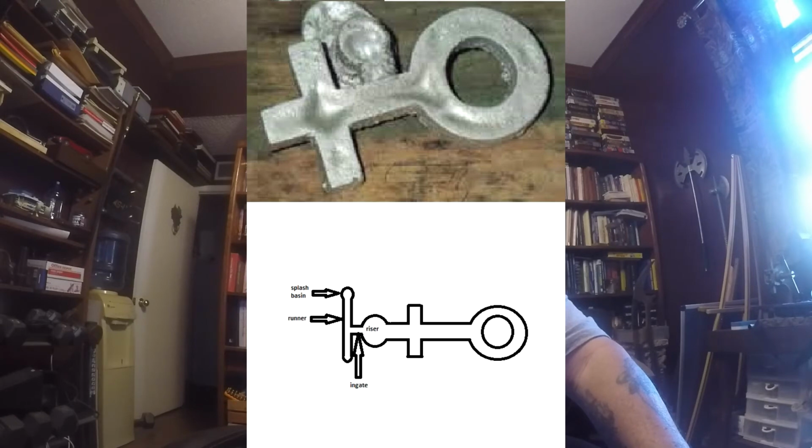And we're looking at the bottom of the casting. Now, the bottom of the casting typically is the best part of it, because all the molten metal that's in there, even if you have dross inside the molten metal, is going to be denser and heavier than anything else in there. Well, it might not be denser and heavier than sand, if you were foolish enough to have a dirty mold before you closed it, and left some sand particles all through your mold cavity.